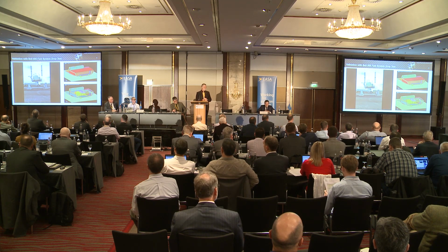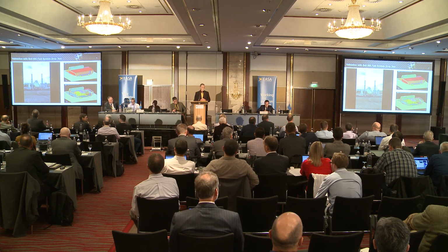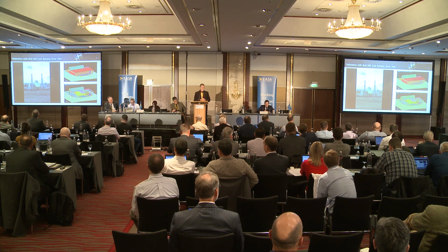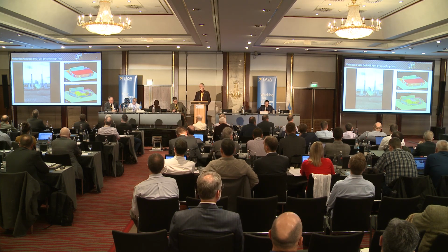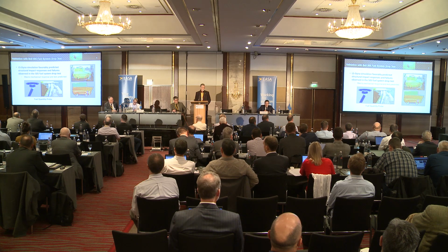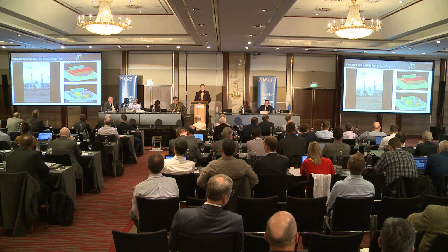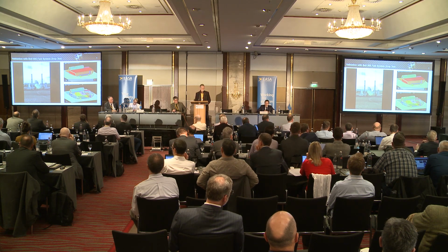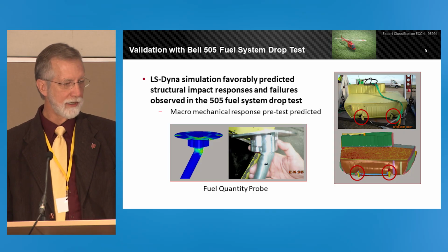This is actually the 505 drop test, the full system with fluid in there, 80% full of water, and the pre-test predictions are on the right. Phenomenological agreement is very good. Macro-mechanical response, you can see, agreed. But in the lower right-hand side, watch the fuel probe that goes down. It compresses against the bottom and buckles, and the next slide shows the results of that.